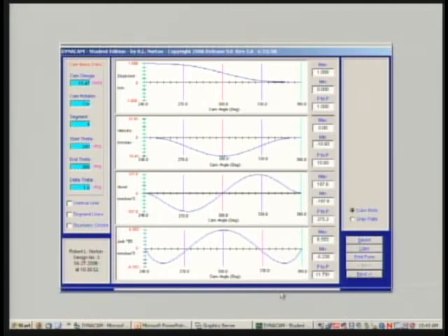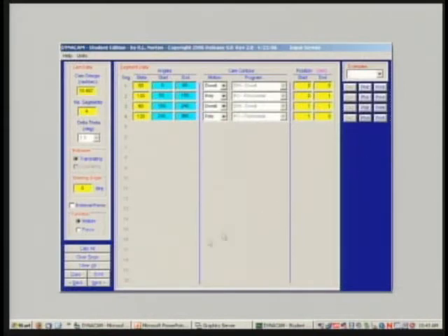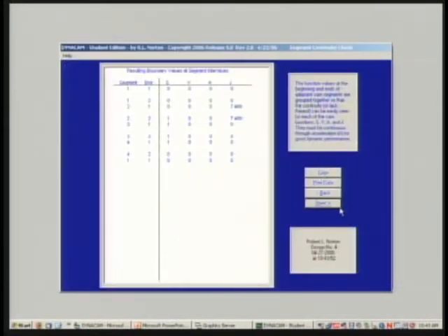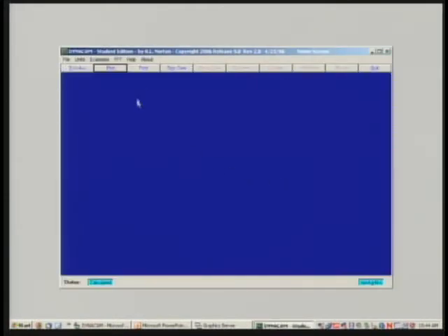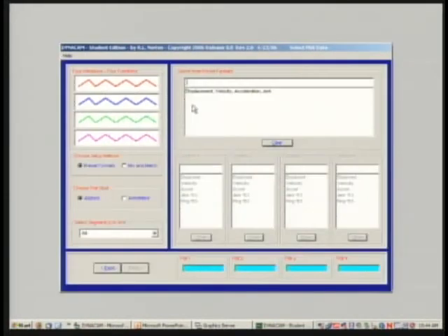That's getting a little bit beyond where I want to go with this introduction, but let's continue. So now I have a new design. Let's go now to our plot screens. On the way there, we see our continuity condition. Notice that between the first dwell and the rise, we have discontinuous jerk, but from the high dwell to the fall, we have continuous jerk because we told it to be so with our polynomial. Let's look at the plot screens.